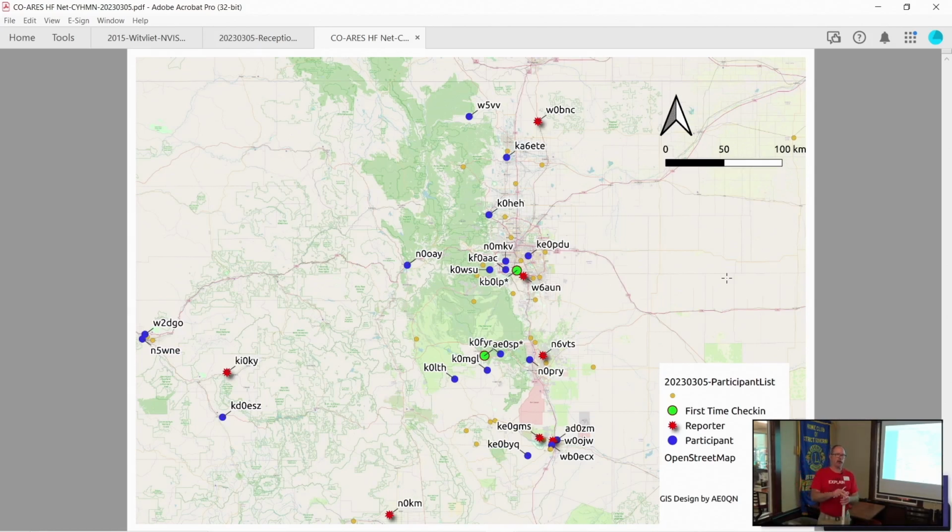One day, years ago, being bored, I took an 80-meter dipole and a bunch of kitty litter buckets, which are 14 inches tall, and used those as supports, and I set up an 80-meter dipole 14 inches off the ground. The first thing I saw was the tuning was way off because capacitive coupling into the dirt that close made it resonate much lower.